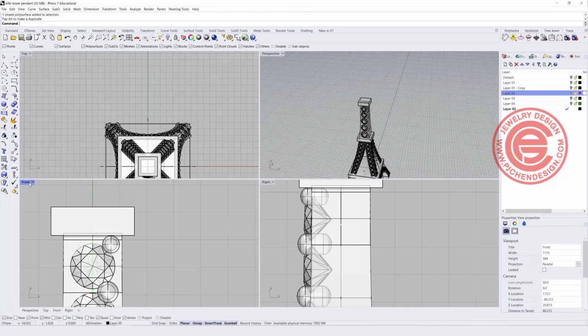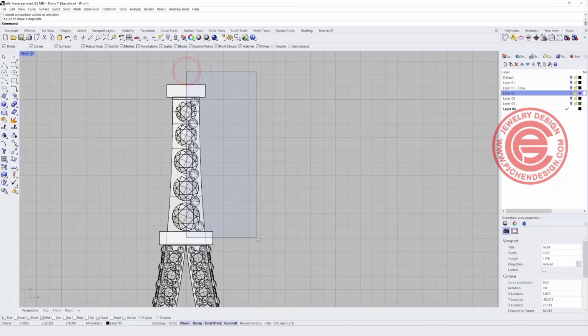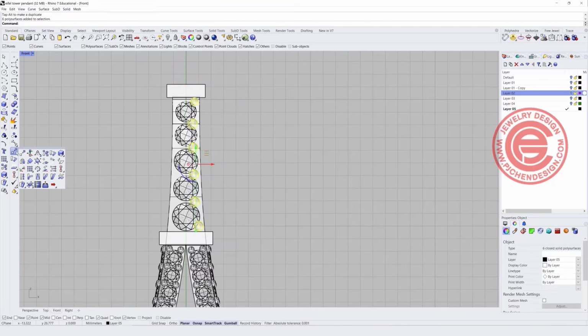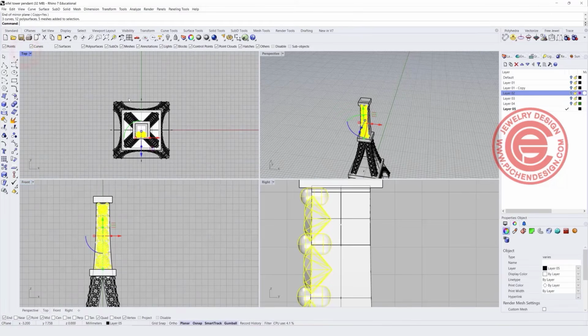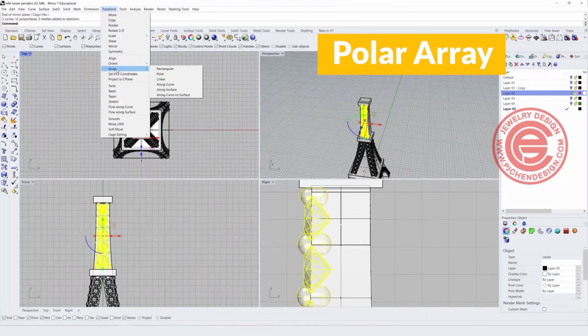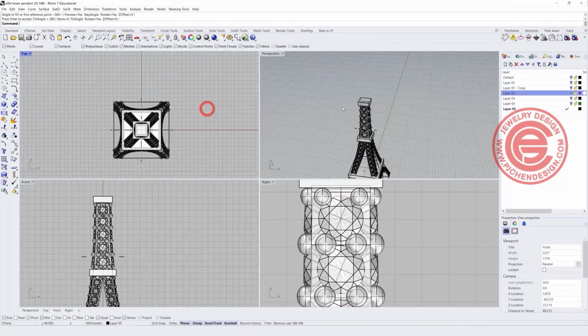All right, once you like your prong and every position is right, we're going to pick up all of this and just mirror to the other side. And if you like everything, let's go ahead and pick up everything. And again, we are going to come into the top view and do the polar array, snapping into the center for 4 of them, and we'll get something like this.